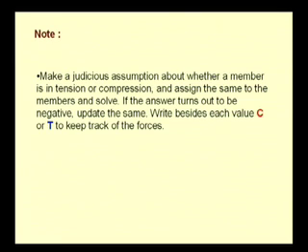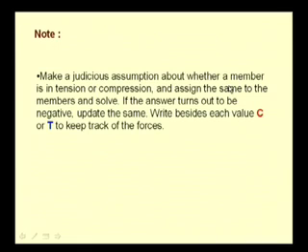Before we proceed to analyze, we have to assume the nature of the internal forces that are existing. We have already seen that the forces can be either tensile in nature or compressive in nature, and we have to assume either of this and accordingly depict the same. And after solving, if we find that the answer turns out to be negative, then we can update the assumption.